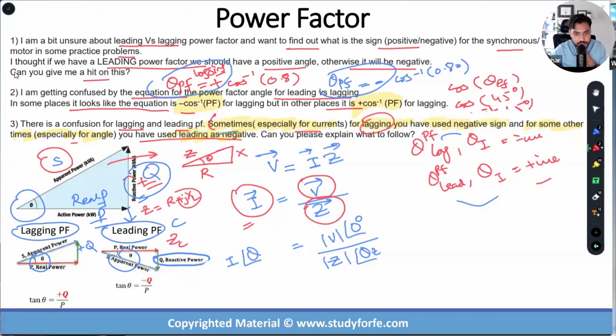If it is a capacitive load, it becomes R minus jXC, pointing downwards, because the capacitive reactance is negative, and that's what leads to that negative sign in Q as well, QC. And the inductive reactance is positive.